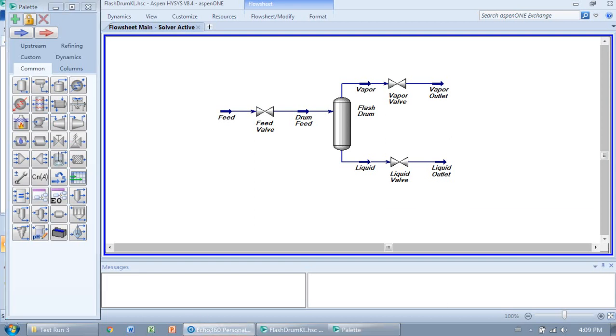So good luck on setting up the steady-state part of your HYSYS simulation, and let me know if you have any questions through email. One final word is make sure you type in the units correctly. I know by default you will have the units in SI, but some of the numbers are provided in PSI, especially the pressure, which you need to type in correctly or things won't work out.